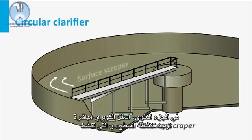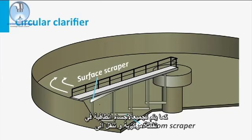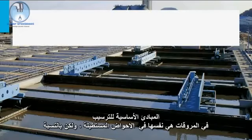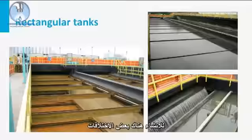At the top part, just under the bridge, a surface scraper is mounted that gently skims the surface from floating organic matter. Also the floating matter is collected at the central point and conveyed to a subsequent treatment step. The basic settling principles in circular or rectangular tanks are the same, but construction-wise, there are some differences.